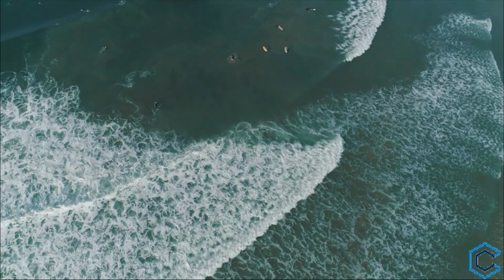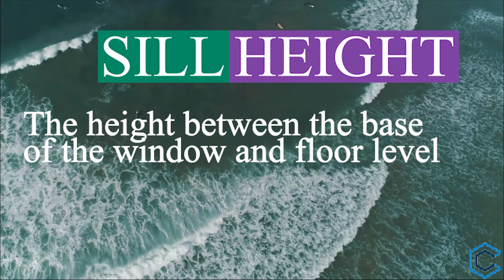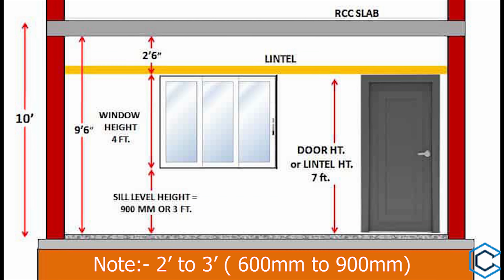So what does it mean by sill height? Sill height is the height between the base of the window and floor level. In general, to ensure privacy, the sill height in bathrooms is kept equal to or greater than 3.5 feet from the floor level, while the sill height for the living rooms and common rooms is kept in the range of 2 feet to 3 feet from the floor level.